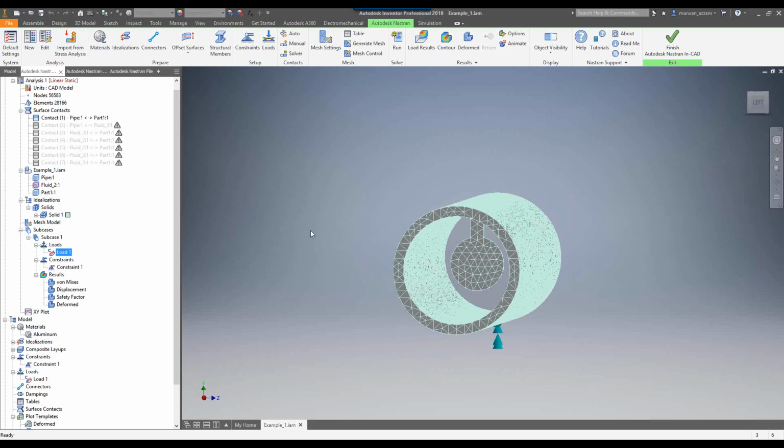I want to add something very important: we need to make sure that both of the models, in CFD and in the FEA program, have the same location and the same orientation, so that you can map the results without problems. That's a very good point, Amal.